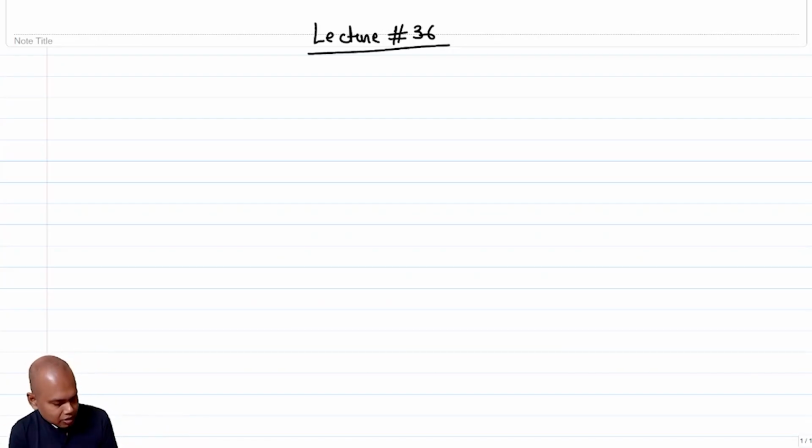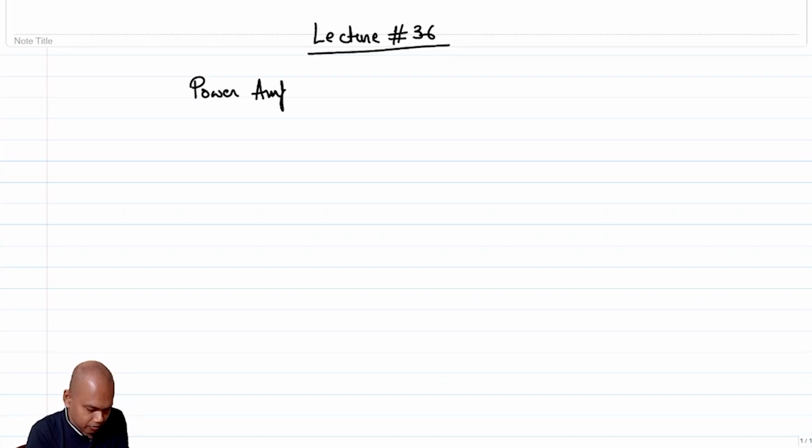So the next part is to understand, once I have everything in the upconverted version, how do I radiate it out? The radiating out of the signal is obviously done by the antenna, but like before, we will assume that the antenna is a 50 ohm load, correct? And so the whole purpose is to figure out how to deliver the requisite amount of power to a 50 ohm load. So the next part of this course deals with power amplifiers.